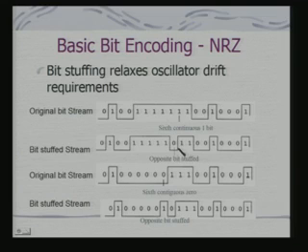Okay. So, what we will see here is that instead of continuous 6 bits, what you have got there is 5 ones, and a 0 bit has been stuffed in, so that the clock can be synchronized if required, because these transitions have to be noted. Similarly, there would be the opposite bit stuffed in case of continuous zeros. So, effectively what CAN uses is non-return to zero and bit stuffing to prevent the problem of clock drifting and wrong interpretation of bit interval.